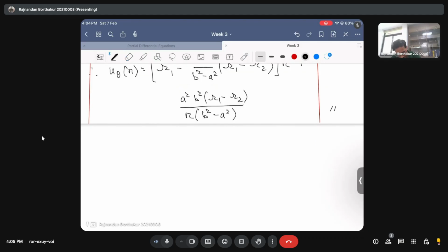Okay, so the second thing is to evaluate uz. And I also know that uz is going to be a function of r. Why? That's because of the assumptions. Fully developed means that uz is not a function of z. Axisymmetric means that uz is not a function of theta. So uz, which can be non-zero, can only have variations in the r direction.